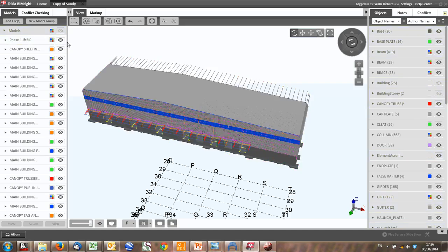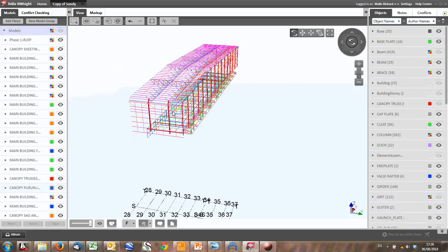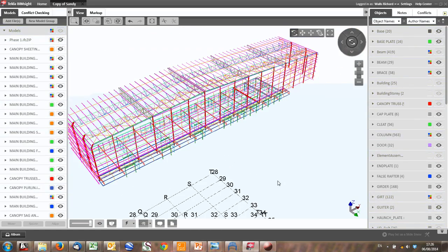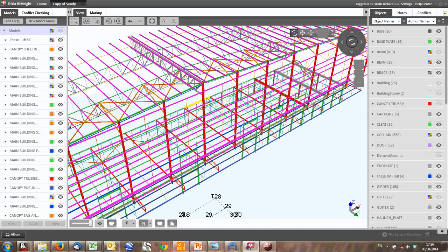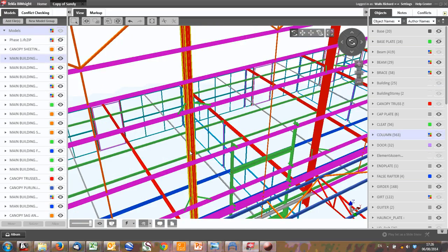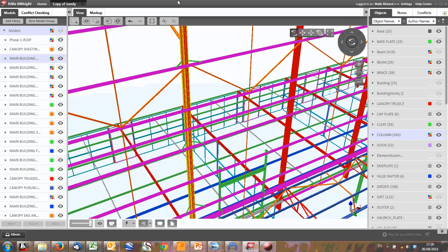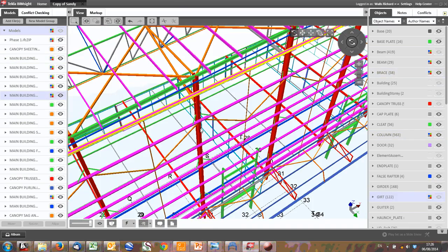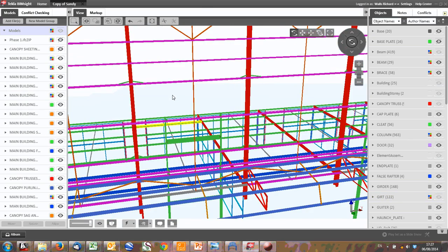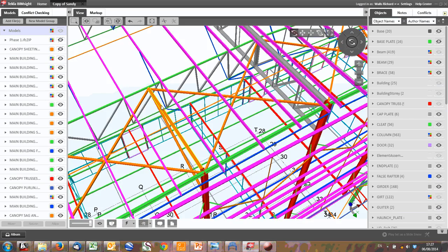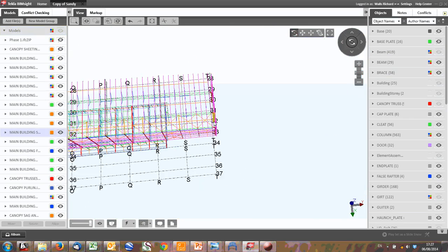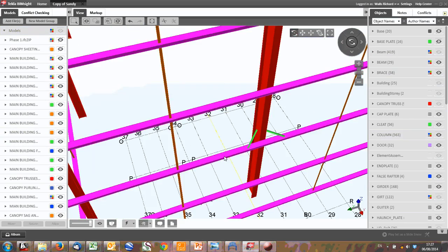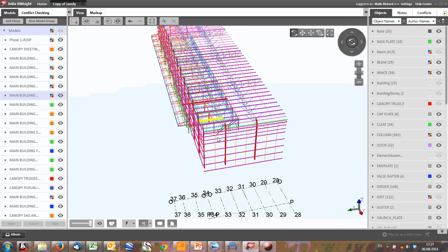So now let me just turn off my sheeting. There we go. Here's our structure. Now where are all the loads going? Wind load blows on the stable column here. Wind load goes up, wind load goes down. As you can see, this had to be stabilized this way, so it carries load to this point. And then it goes down the roof brace, all the way to the end. Uh-oh, no vertical bracing. Why is that? Why is there a problem?